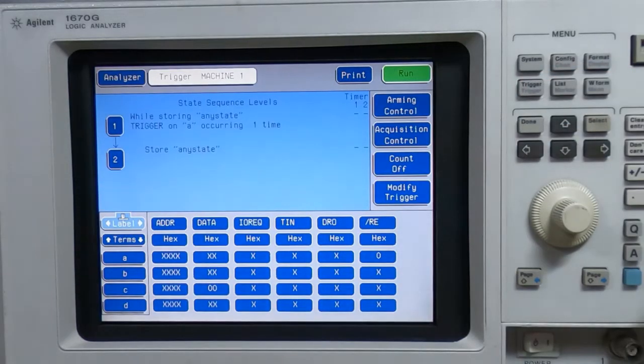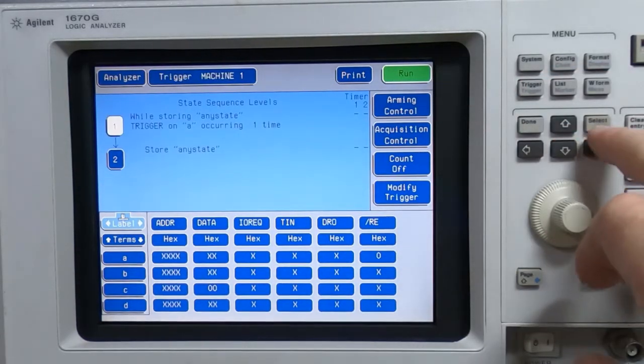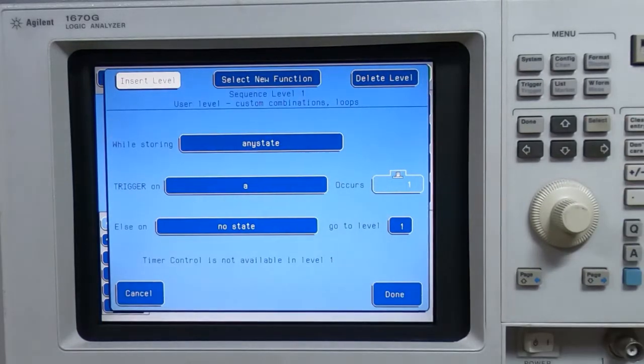Okay, so what we need to do in the trigger is to set the number of hits on this particular event to make sure that we select the next value that's read from the floppy drive controller. So we're getting 12 clock edges from the Z80 clock between the data value being read and the next event on the data bus occurring. That's when the trigger will stop being hit on the analyzer.